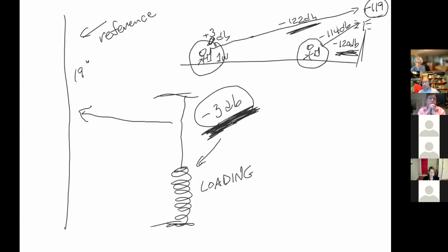Like, I've actually seen an antenna that's for sale, I think it's called a stubby duck, and it's only 2 inches long. And it's still a 50 ohm impedance antenna, which means your radio's happy. The whole thing is 19 inches of wire coiled up in a 2-inch thing. It's only 2 inches tall, right? That's really convenient, but its gain actually might be minus 10 dB.